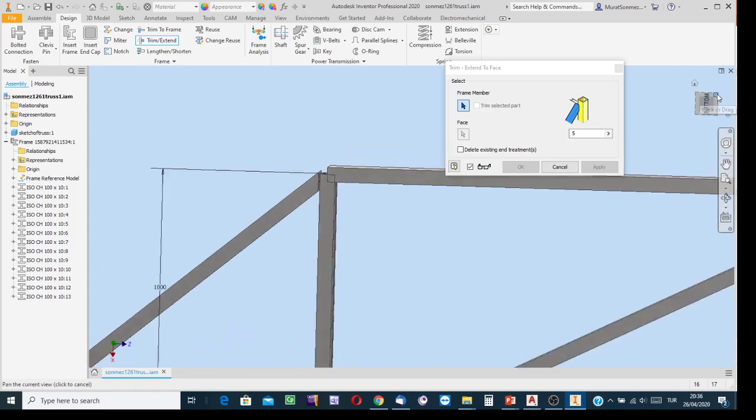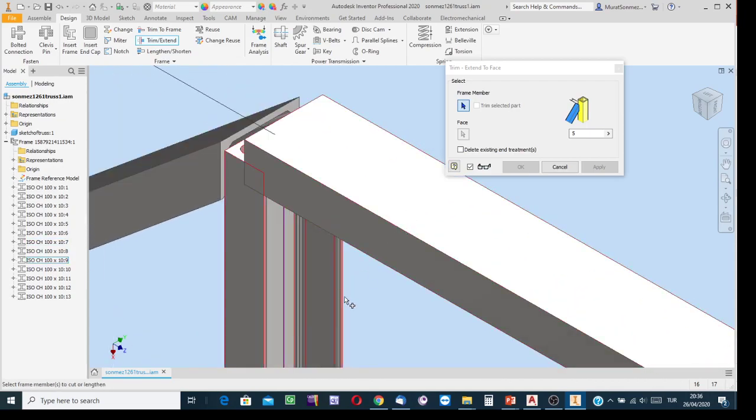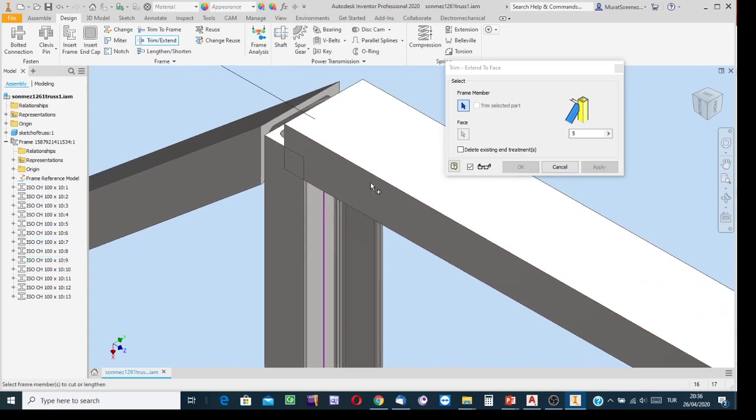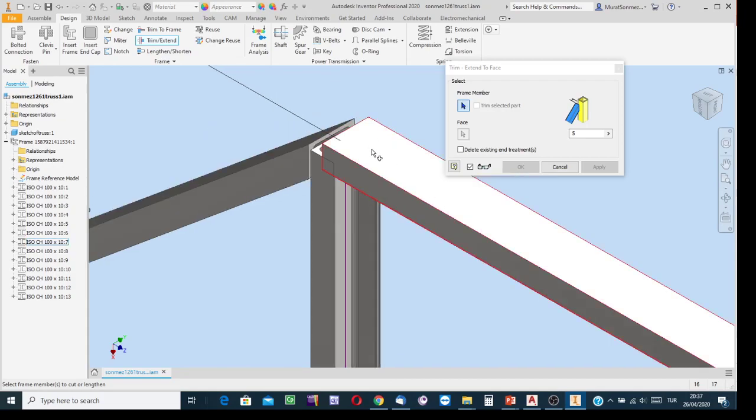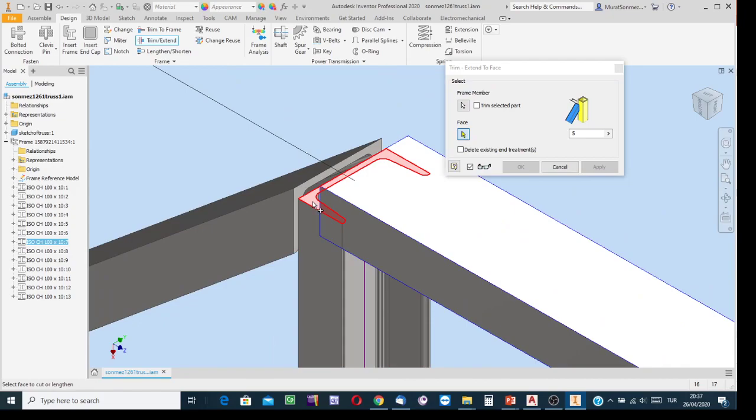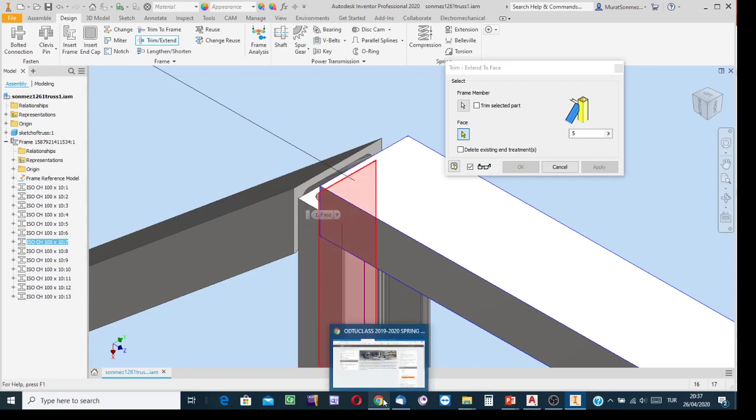Continue. And then, here, this side. Shall you trim the end of this or the end of the other? Because they are interfering. Decide which one. Okay, I'm going to trim the end of this one. So indicate this one, click on the face indication button, and it is to say that after this surface, I have an interference, to this surface chop it. But here, if I chop it, then here it is going to be necessary to indicate this one more time and that one as a target.